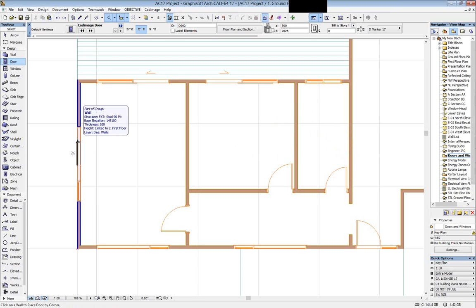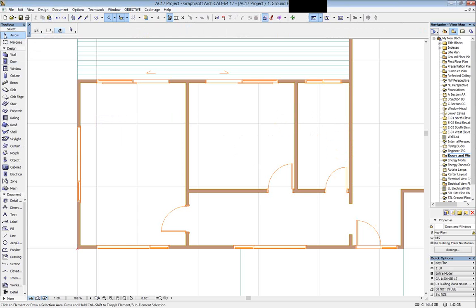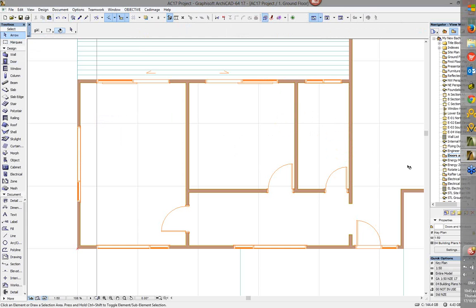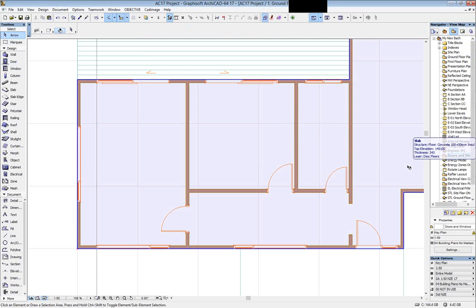But there is quite a lot of little things to know about STL files that we have learnt through experimentation, and we figured we'd just give those lessons to you so you don't make our mistakes. The first one is size. 3D printers are still limited in terms of the actual size they can print. So whenever you're printing a model, you've got to be aware that you might not be able to print the whole model in one go.